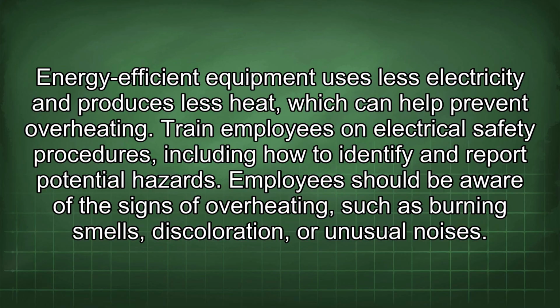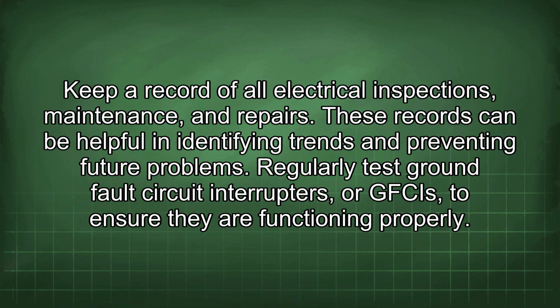Train employees on electrical safety procedures, including how to identify and report potential hazards. Employees should be aware of the signs of overheating, such as burning smells, discoloration, or unusual noises. Keep a record of all electrical inspections, maintenance, and repairs. These records can be helpful in identifying trends and preventing future problems.